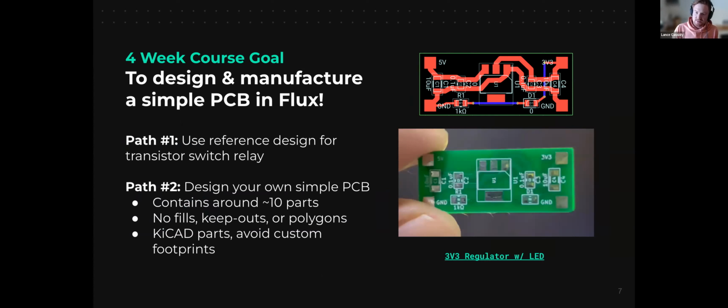It's kind of cool. And then the other concept to understand is that you can nest parts within parts. So parts can have an internal schematic diagram. They can also have what's called a sub layout, and these are the things that create these compounding effects. So you can create modules that have internal schematics, so they can work at a module or systems level. And that can enable some really cool workflows as well.